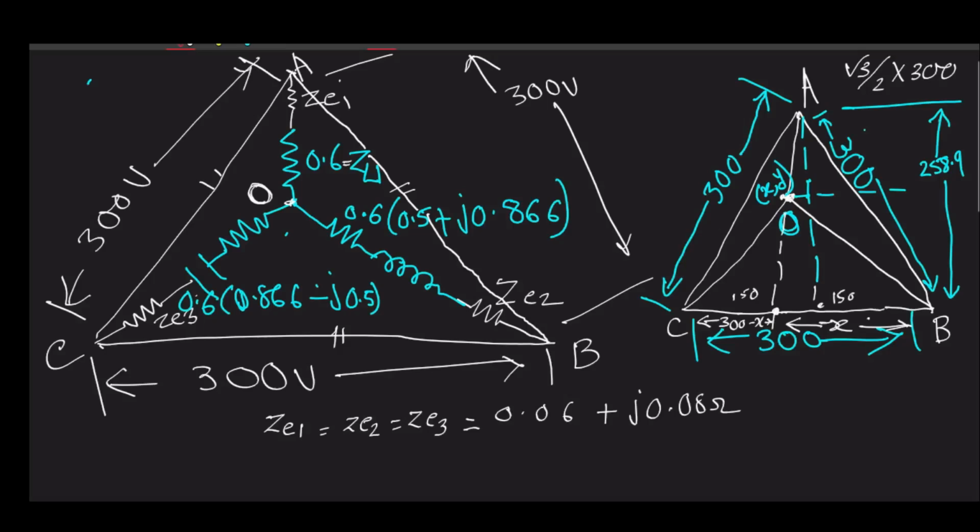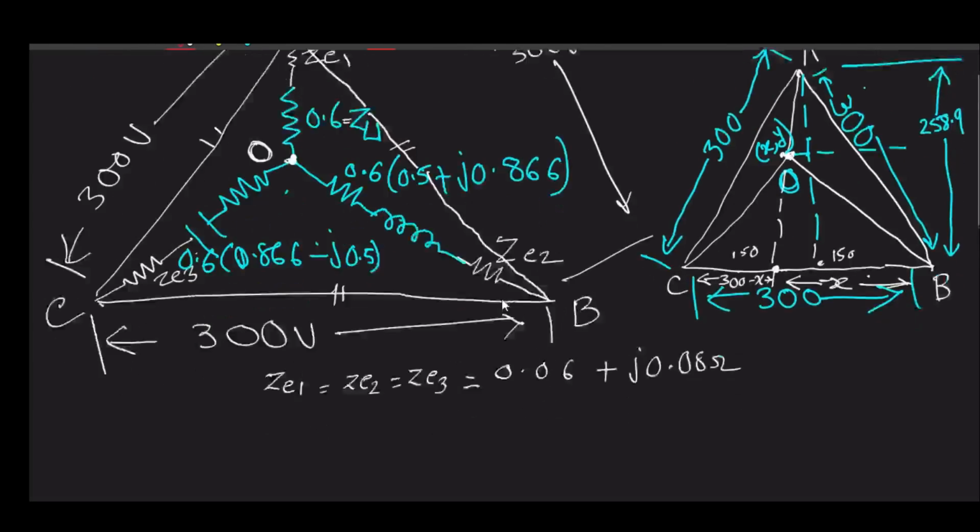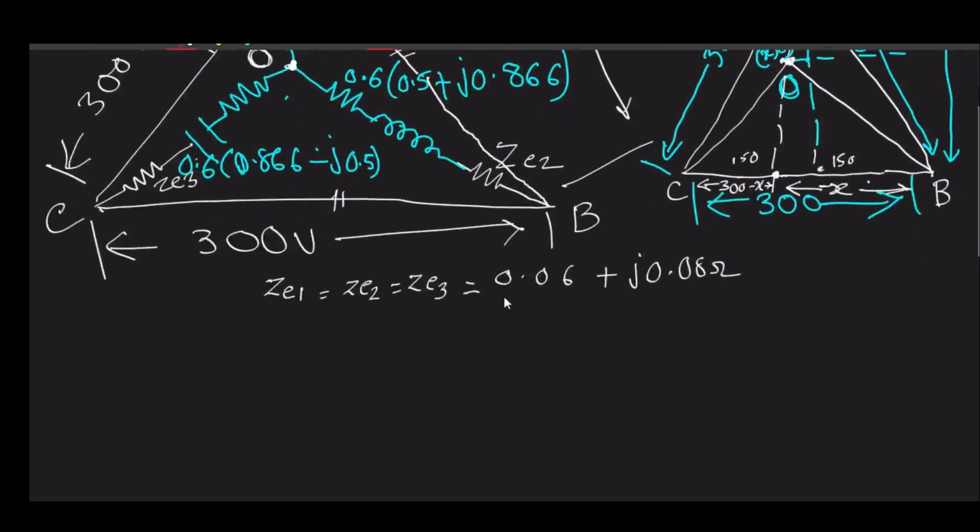Then we will get the load currents IA, IB, IC, and as they are connected here, they are bound to obey KCL. So eventually we can write IA plus IB plus IC is equal to 0, and that can give us the result. In solving them we can find out x and y, and then obviously the voltages and currents. Anyway, so let us write the voltage equation.